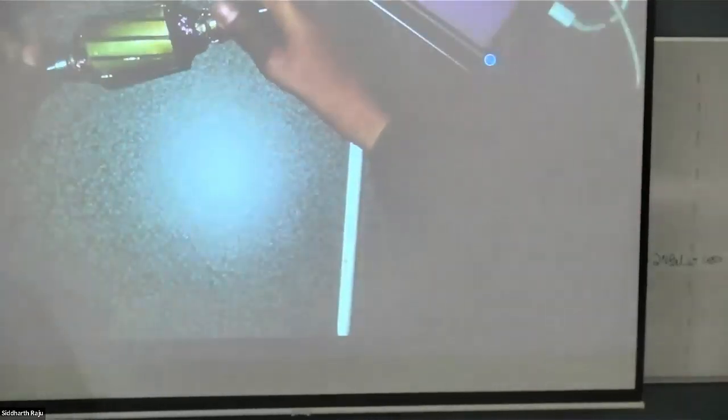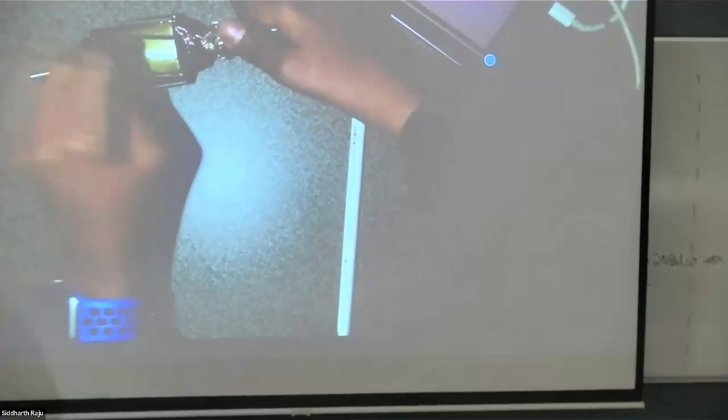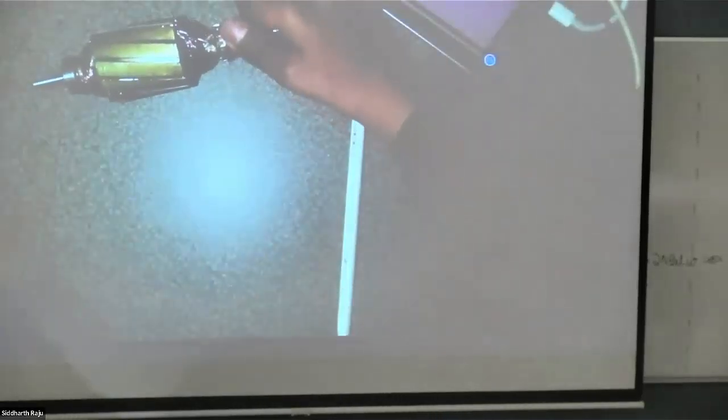So what we have here is the rotor structure. The way the rotors are made, it is not a single iron that's being chopped and cut into, right? We have these thin plates, I'll show another diagram for that, that are stacked together. You can't see that very clearly here, but I can pass it around and you'll see that these are all actually thin plates of iron stacked up together, each iron insulated from one another, laminated from one another, so that they don't electrically conduct.